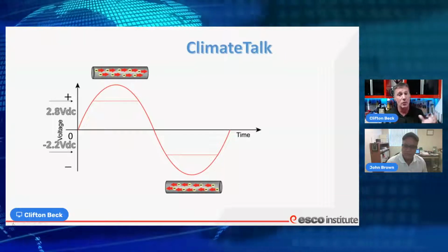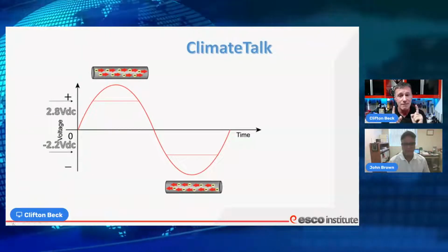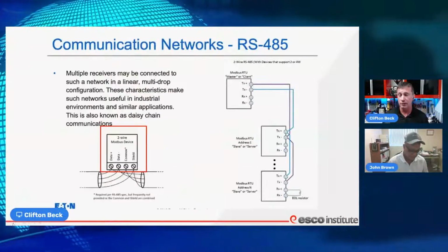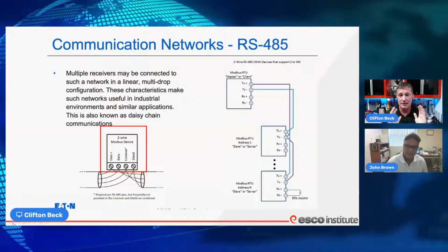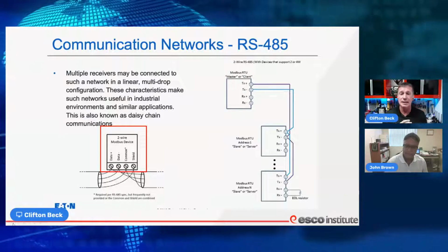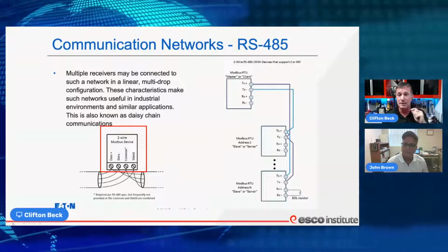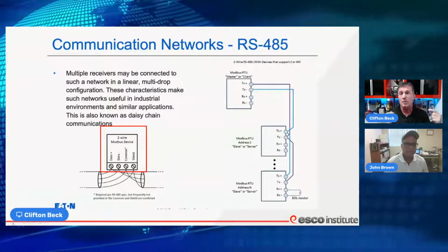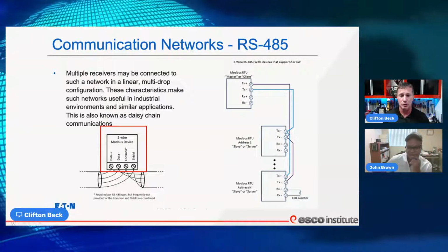Well, when we talk on that, we're not going to be able to listen in on what's being said on that, but we can verify if our network is working properly so that we can start looking for issues, right? So if we reflect back on this RS-485 platform, we can see here in the little red square that it is a 2-wire data function primarily. This one is going to call it data plus and data negative. And then we might have our common and our ground, which is for our communication cable. But the work is really being done on those 2 terminals.